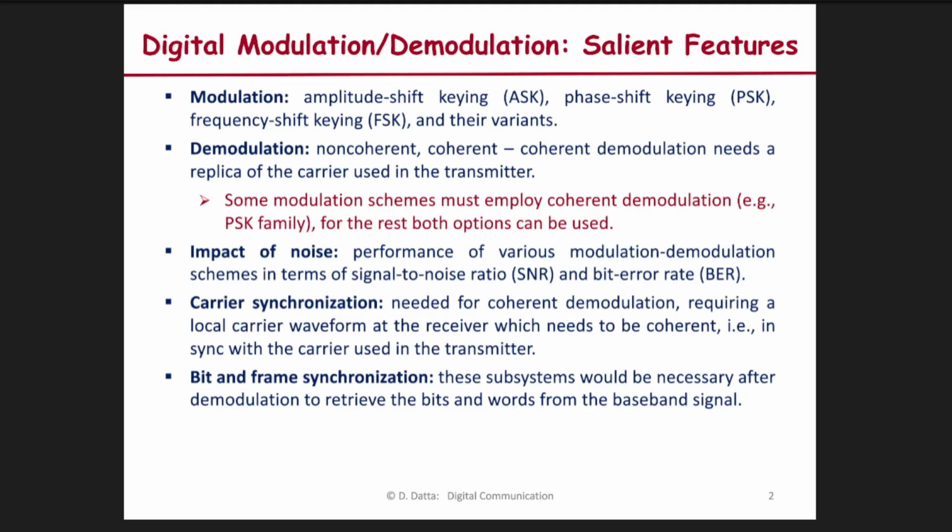Now you can take all the n signals and simply add them up, sum them up. Then you get the spectrum of the multiplexed signal. You can see that multiplex signal. So n number of speeches are now available together, and you can transmit them simultaneously over the same medium, be it radio, wireless, or any transmission line like coaxial cable, by using modulation and multiplexing.